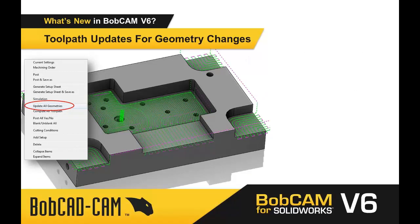The third topic here is going to be Toolpath Updates for geometry changes. Ask yourself, are the latest design changes reflected in your toolpath? Maybe you changed that hole location, or maybe you added additional clearances. These are common things; design changes happen. Is your toolpath updated for those design changes?